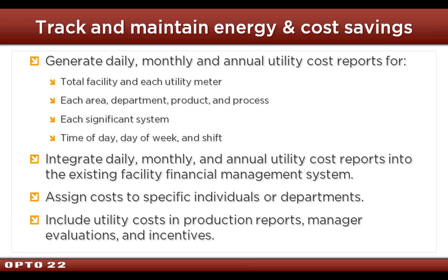But you do it for the total facility, each meter within a facility, each area, each department, each significant system. We were in a Honda supplier plant, and we actually put in instrumentation so they could break out their costs, their unit costs, and include energy. So every production line, every part. Before, they were doing it on a square foot basis, which for industrial plants where maybe half their cost is peak demand, that's a horrible way to do it. It's not accurate at all, but it's all they knew how to do.